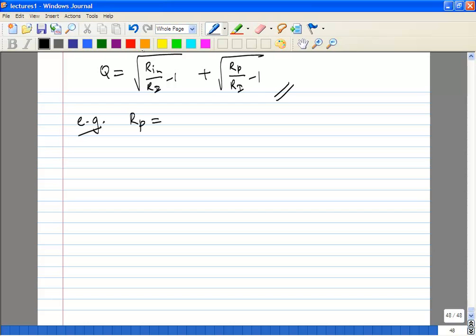So let's do the same thing, right? Rp equals 200, Rn equals 50, so 200 ohms and 50 ohms, and .4 gigahertz, right? But we are going to add an extra condition that the Q should be 10. What was the earlier Q when we did this using the L match? 1.73, right? Root 3. So it's very small, which means it's a very broadband match. But suppose you need a very narrow band match, right? So let's put this condition that the Q is 10.